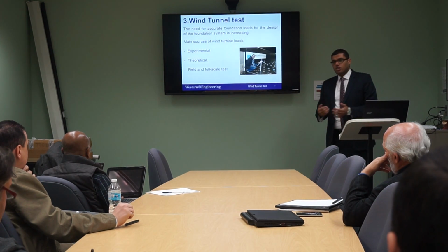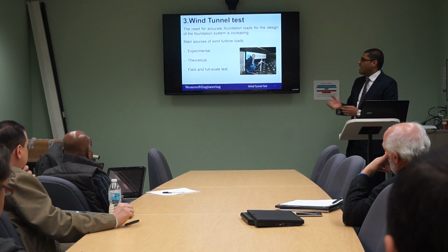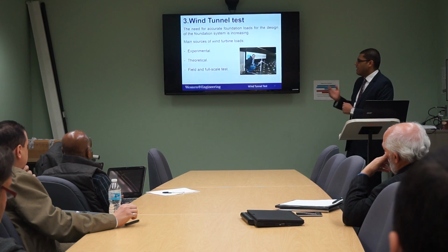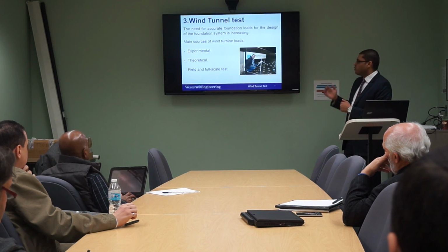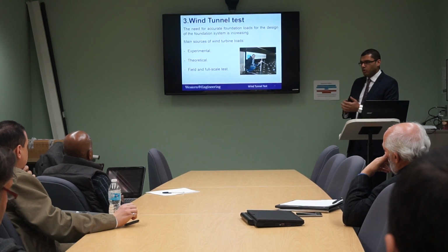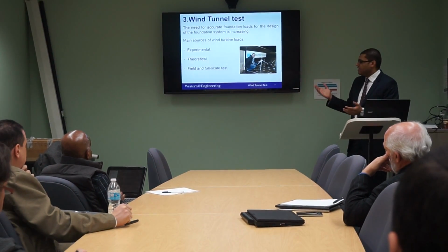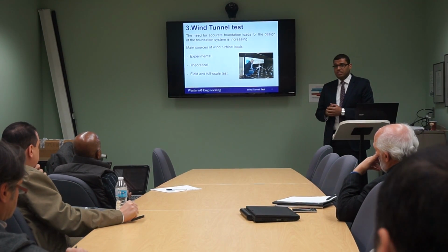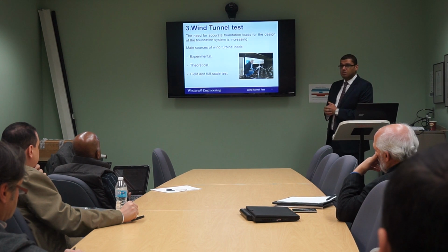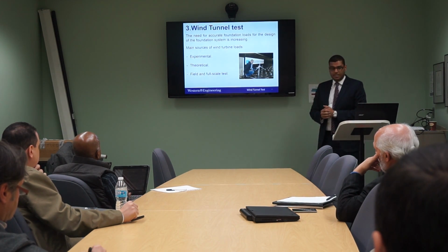Generally, to get accurate load, we have several methods. We have experimental, we have theoretical, we have field. The experimental one would be the wind tunnel. We have theoretical by using programs such as CFD, and field and full scale tests, which in some cases would be so expensive. So for our experimental work, we chose the wind tunnel test.